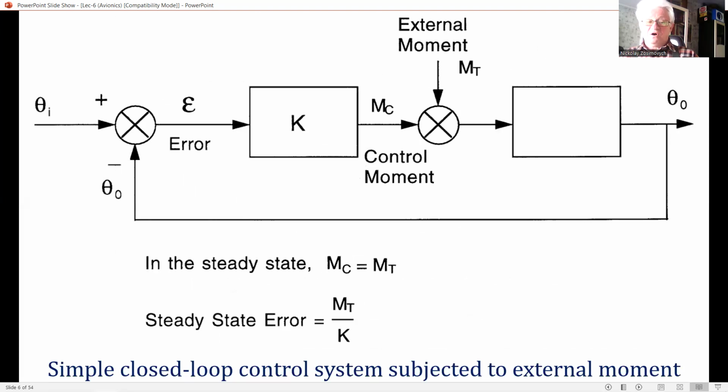Proportional plus integral of error control eliminates steady-state error and reduces the following lag. The integral of error term increases the loop gain at low frequency, up to theoretically infinite gain at DC, so that there are zero steady-state errors due to out of trim external moments or forces acting on the aircraft. The error when following a low frequency input command is also reduced and is zero for a constant input rate.